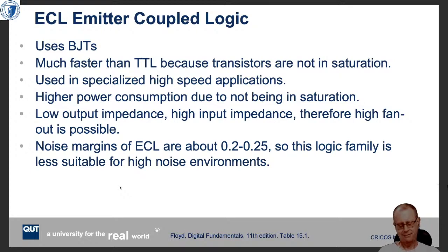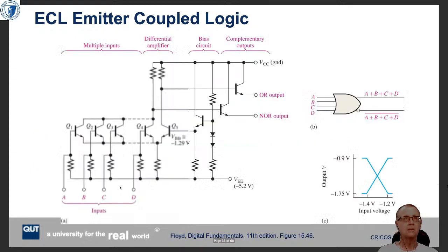And so that's where the emitter-coupled logic comes in. And here's an example, right? And the reason it's called emitter-coupled logic is because this is the way, right? The emitter is connected directly to the output, and there's nothing else there.